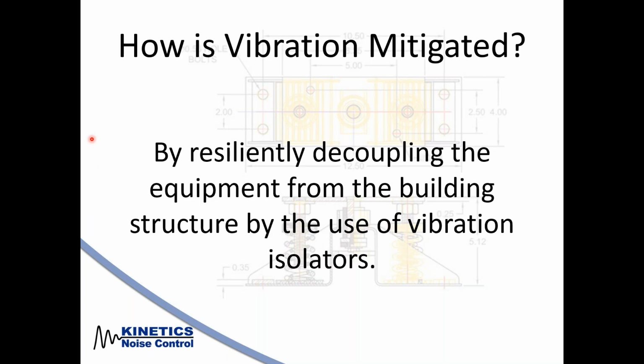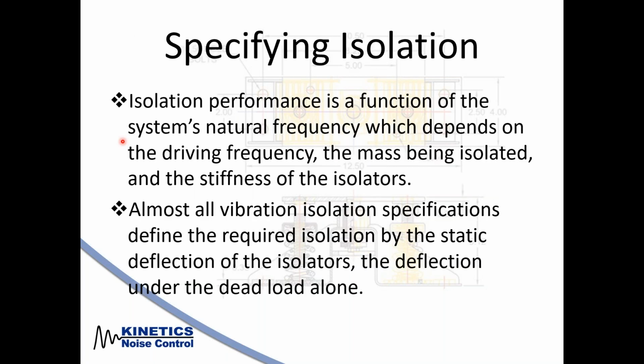So how do we get rid of that vibration? Basically, we resiliently decouple the equipment from the building structure by the use of vibration isolators. So we'll put the equipment on something that's going to absorb the vibration to stop that vibration getting through to the structure itself.